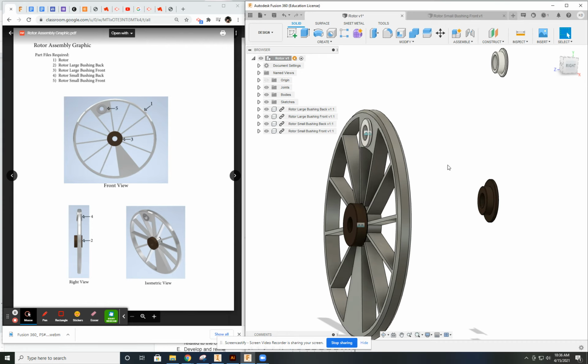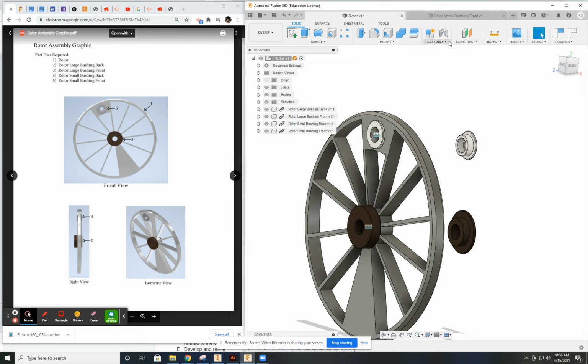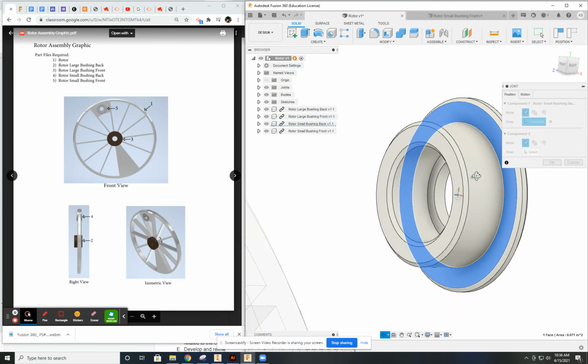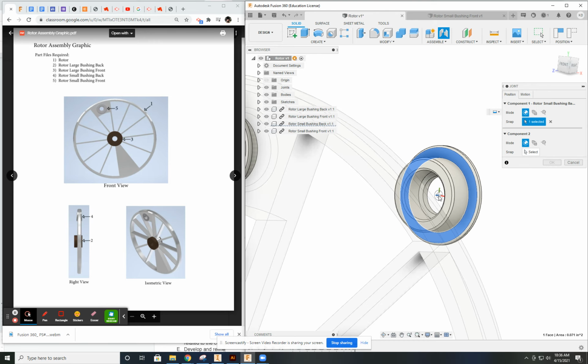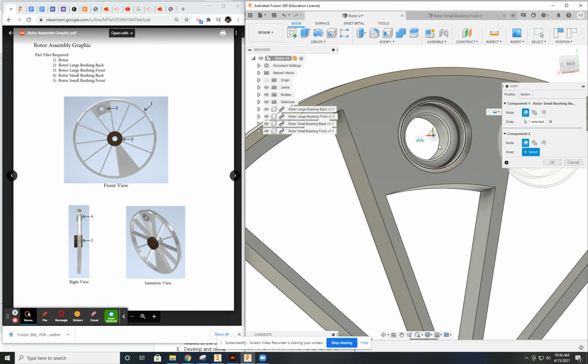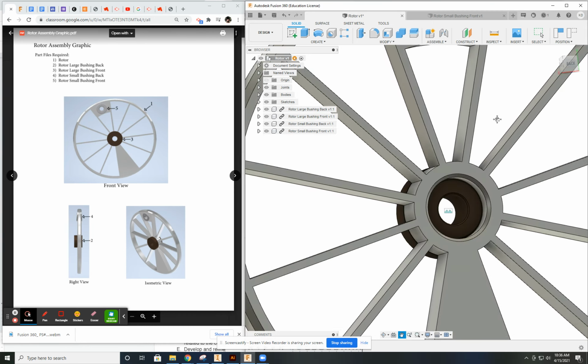Okay, so I have the 2 front joints. You would just repeat the same process with the joints on the back. Very simple. Just take your time in where you're clicking and understanding that these little mini origins are going to become coincident, or line up with each other. If you understand that, it all does what it's supposed to do.